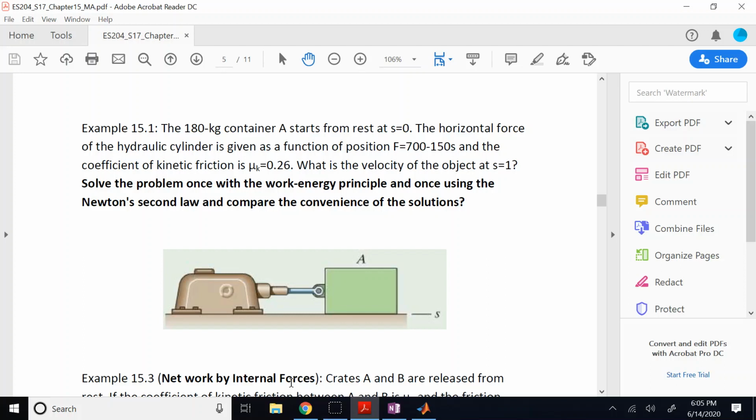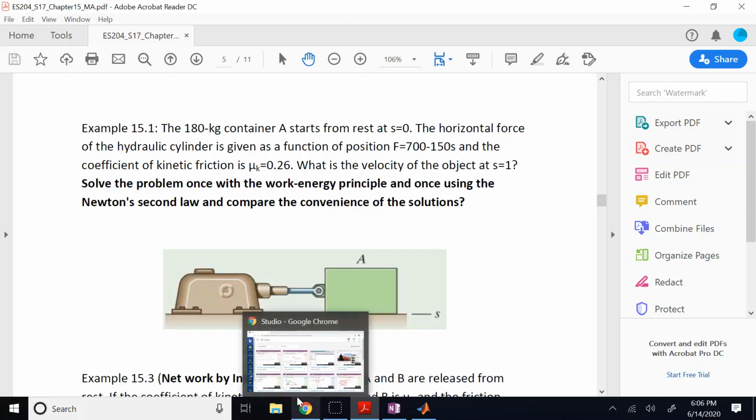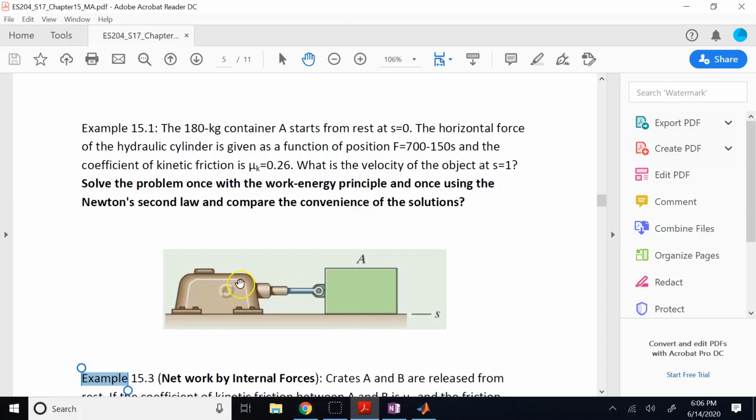In other words, the further the cylinder expands, the force goes down. Is that correct intuitively? Yes, because when this hydraulic fluid that is under pressure is expanded, it is going to lose what? When volume goes up, pressure goes down, and force that is applied to the piston is pressure times the section area. The section area is constant, but when pressure goes down, the force goes down. So clearly you can see why the force is going down as it expands.